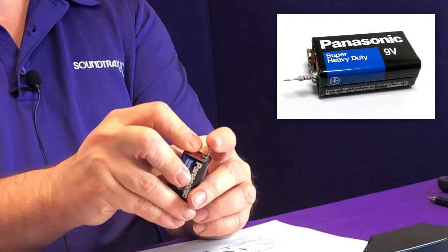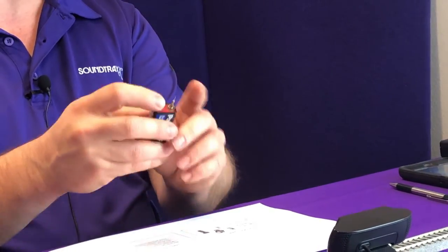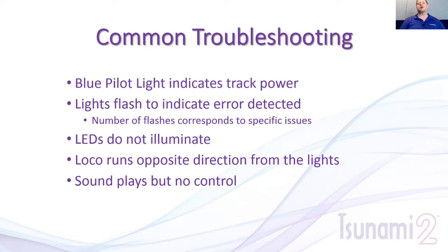And first of all, that tests the LED to make sure it lights, but it also allows me to confirm polarity. So when I'm actually wiring it to the decoder, I can make sure that my polarity is correct. So once you have that in there, again, when you're wiring in your LEDs, you want to make sure you put your resistor in there.